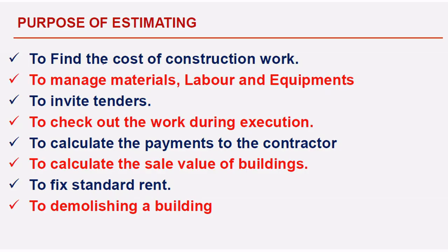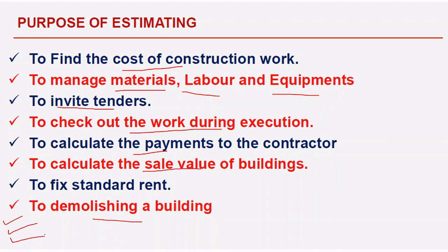Okay, so next, what is the purpose of estimating? So here, to find the cost of construction work, to manage materials, labors and equipments, to invite tenders, to check the work during execution, to calculate payments to the contractor, to calculate sale value of the building, to fix standard rent, to demolish a building, estimation is required. A few more points you can add once you go through the subject.